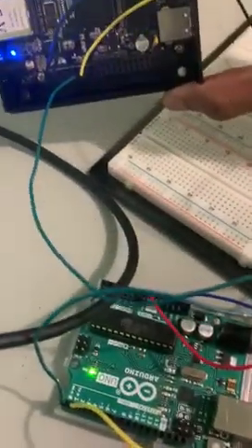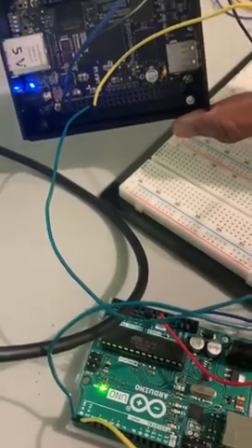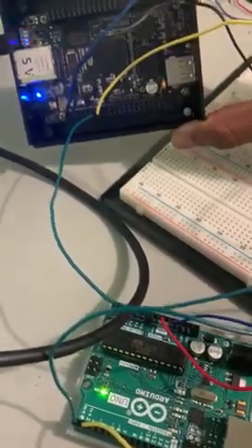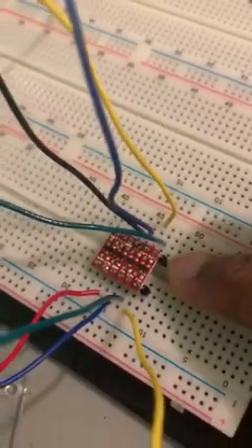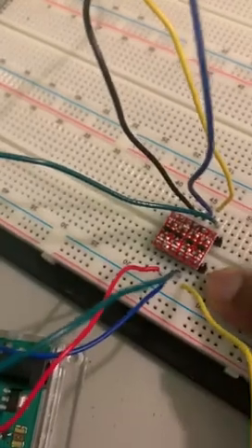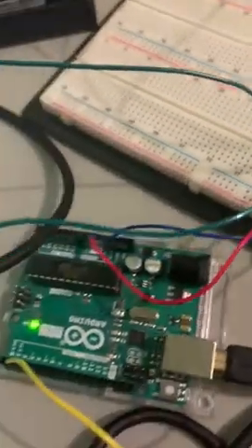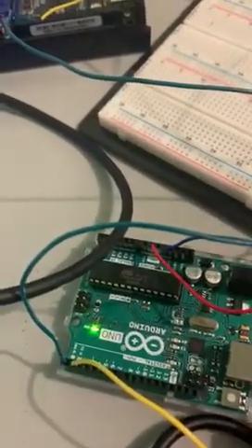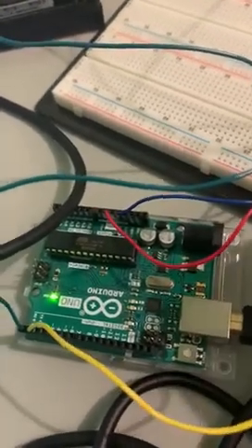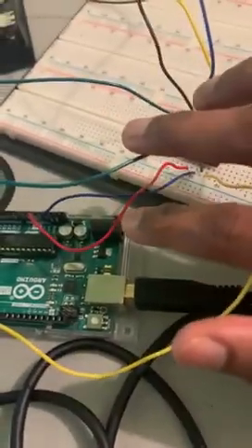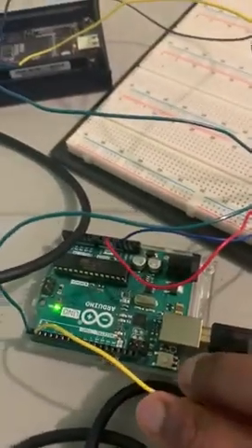We have made use of UART 4, which corresponds to pins 11 and 13 of the Beaglebone, and that's connected to the low voltage levels of the logic level converter, and the high voltage side is connected to the Arduino board, which corresponds to 5 volts. And we have connected all the power and ground pins as well as the transceiver pins. And now